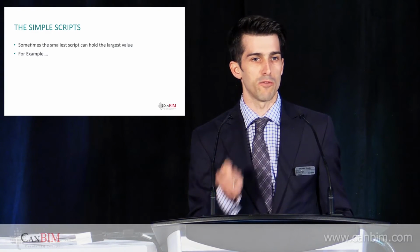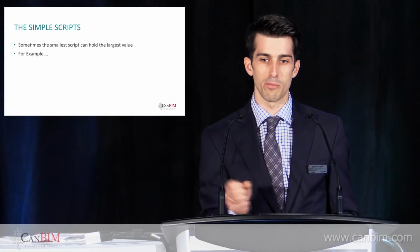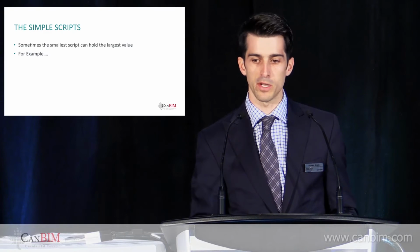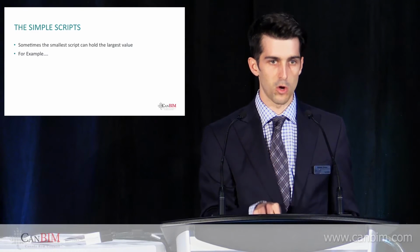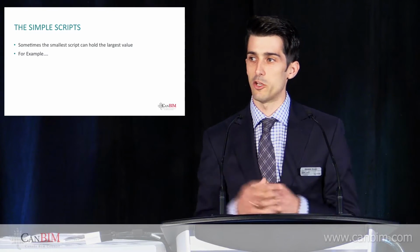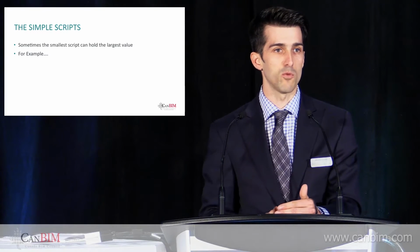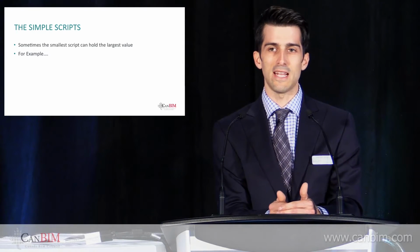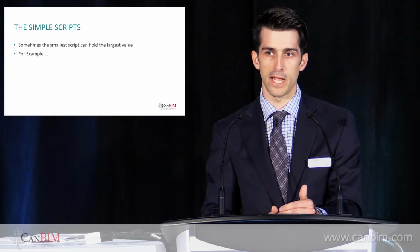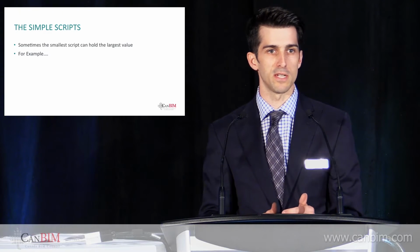So if I wanted to refer to interior design on all of my doors, I could place that exact text into my instance parameter just by going into Dynamo, saying go, and it inserts that into my schedule in a mass context. I can use Dynamo to generate, for instance, a level renaming, or take every single piece of text in my entire project and make them all uppercase, because I know that comes into contact every now and then when drafting.